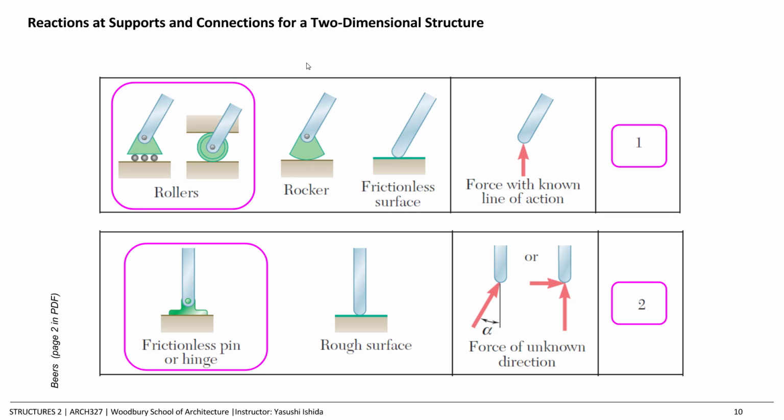But it has resistance to vertical loading. If you try to push it, it's going to provide a reaction. The next point is slightly tricky to grasp, but it also has a reaction the other way. So it won't squish, but you also cannot lift it off, which is weird to think about, but that's how the roller joint is defined. It moves this way, but it cannot move up or down. Does that make sense?